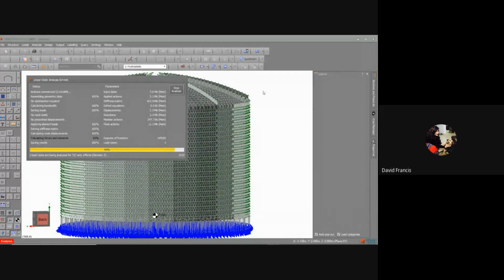By the way, when I ran this, I ran linear static. I can run nonlinear, and we have nonlinear plates, and there is a tremendous amount of help in SpaceGass. So once you've got your versions of the software working, for any of the dialogues that come up on the screen, refer to the helps, and you get a lot of information, a lot of technical detail as well. And there's a lot of information about the nonlinear plates and the theories that we're using. So there's large deflection theories and small deflection theories based on the plate types that we've got.